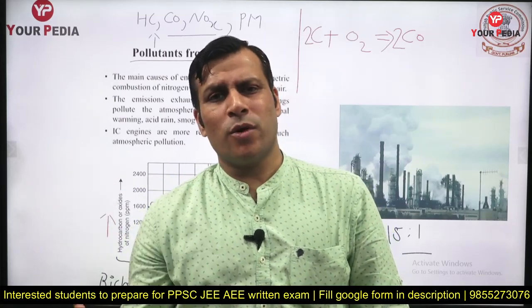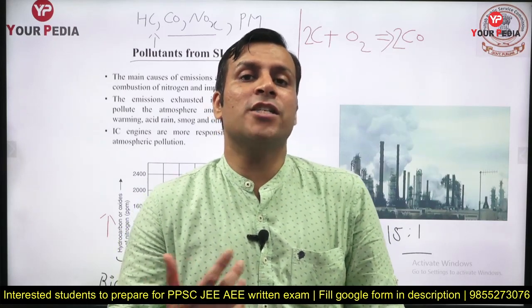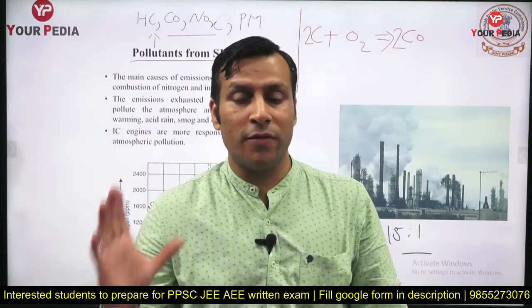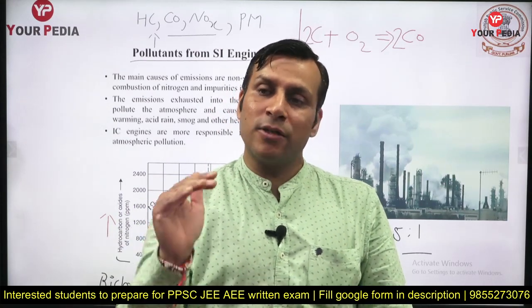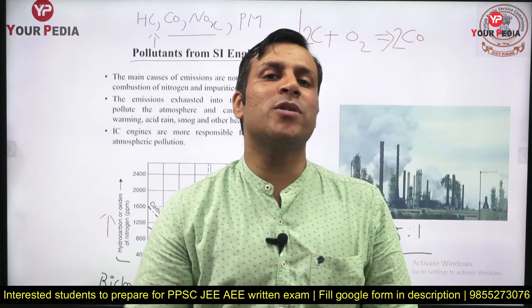Those are much more further technical things. Why actually is a rich mixture required? Because some kind of charge dilution takes place in the engine when your valve is almost closed, because the accelerator is not on, the throttle is almost closed. In that case, if you are supplying a lean mixture, you will not be able to sustain the combustion. Your engine will automatically turn off.